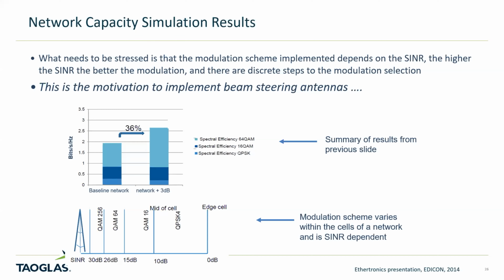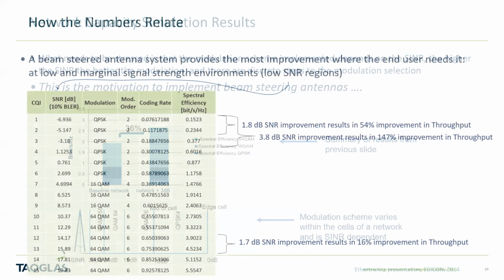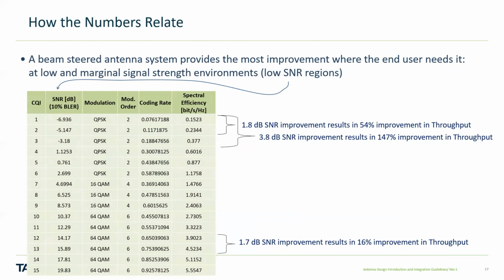So if we can get control of the radiation pattern of an antenna on a client device, increase the directivity, not only do we improve the S, but we also improve the I in the SINR. We can put more energy on a node, and we can start to null out or put less power on other nodes, i.e. interference mechanisms. So it's a very strong technique. This chart here just helps to drive home, again, that fact.